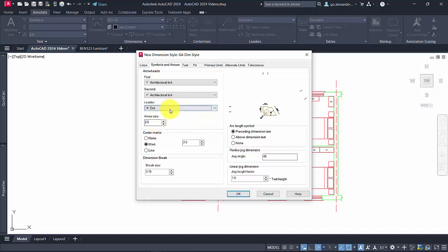This is what I generally use for my dimensions for angles and various things like that, although it's unlikely we'll need to use any of those. Potentially maybe for something on the elevation, but we'll see at a later point. So the arrow size needs to be 100, and again this makes the preview window look very odd at this stage, but let's not worry about that.